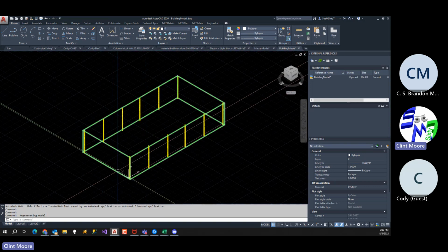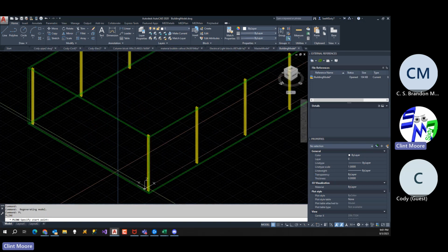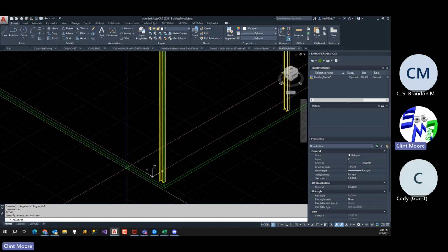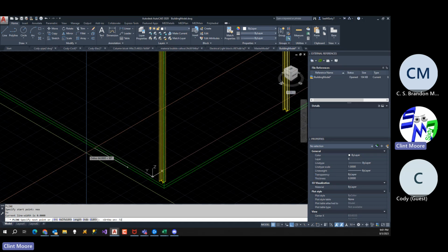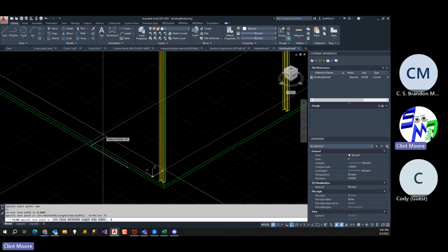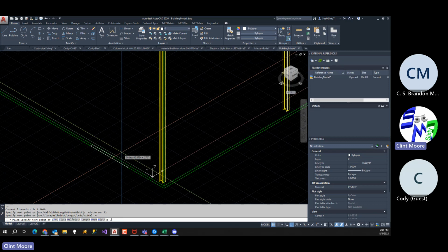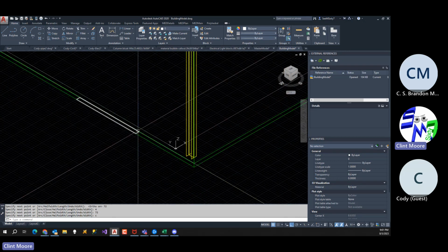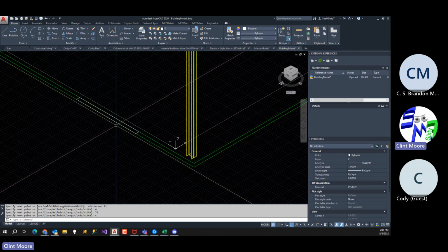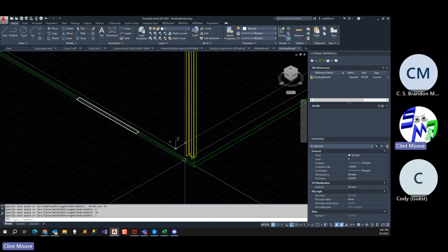So I want to cut a 6-foot door over here. I'm going to actually draw it right on the wall here. I'm going to say from near here, and drag up here. I'm going to say 72 inches. Boom. And then I'm going to come across here 4 inches, and then 72 inches and close. Boom. Now, if I wanted to move this to a more precise location, I could do that, and move it up like 6 feet from here, whatever. I'm not worried about that right now.